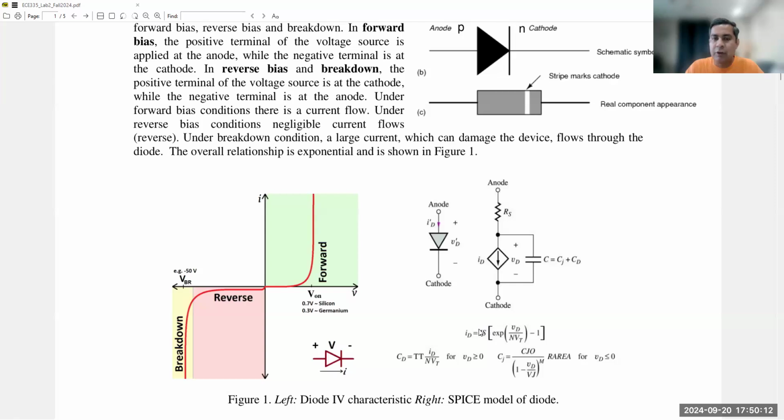That is also a diode characteristic parameter that we are going to derive and deduce from the devices that we are examining. Usually for a diode, it shows how much your current will be in the reverse direction until it breaks down. So that is the third phenomenon, which is the breakdown region. That happens when we apply a large voltage across the diode in the reverse bias condition.